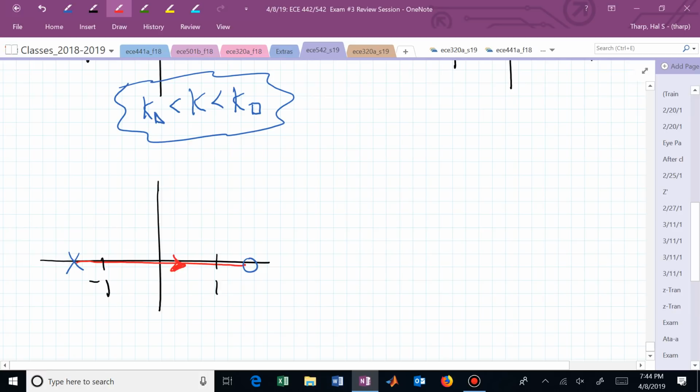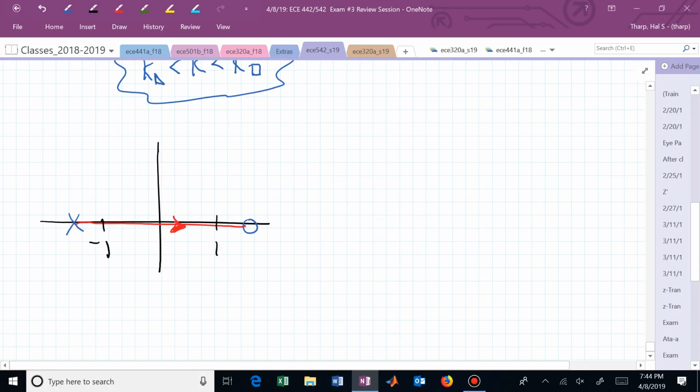And now do you see that, in fact, I've kind of flipped this on its head in terms of where I evaluate z to find the minimum gain and where I evaluate z to find the maximum. There would be K min, and that's now going to be K when z is equal to -1.